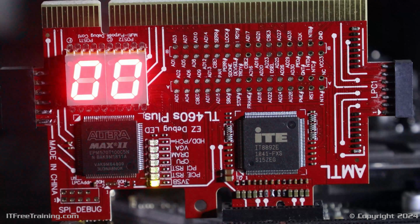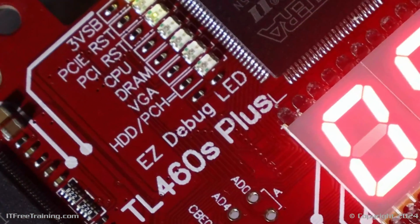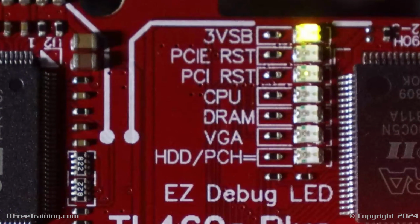You probably missed it, but the PC postcard also has an Easy Debug LED section. But notice that the light for CPU has not activated like it was on the motherboard. The problem is none of this information is being sent to the card using the PCI Express slot, so I will use the card in a different connector to get it to work.